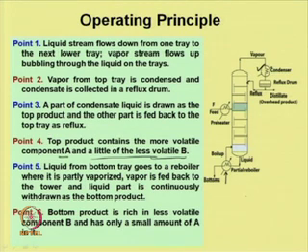It is partially vaporized and the vapor is fed to the tower, and some bottom product is continuously withdrawn. The bottom product is rich in the less volatile component and has very small fractions of the more volatile component.